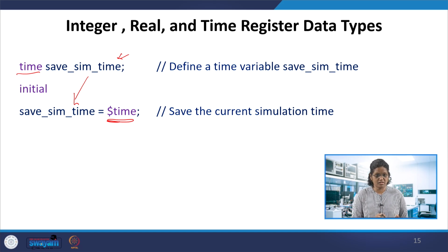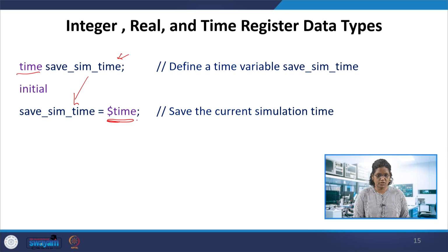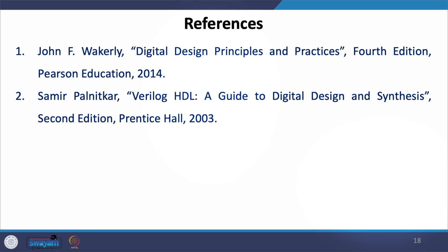So we have seen some of the syntax, nets and variable declarations in this lecture. Also how literals and numbers can be specified. Different types of net types, with the details, we will cover in structural modeling, including wire and wire-or, truth tables and everything. Also the time declaration, the real, integer and reg declarations, and the difference between reg and wire declarations. The wire comes under the net declaration, whereas reg and integer come under the variable declaration. These details have been covered in this lecture. Thank you.